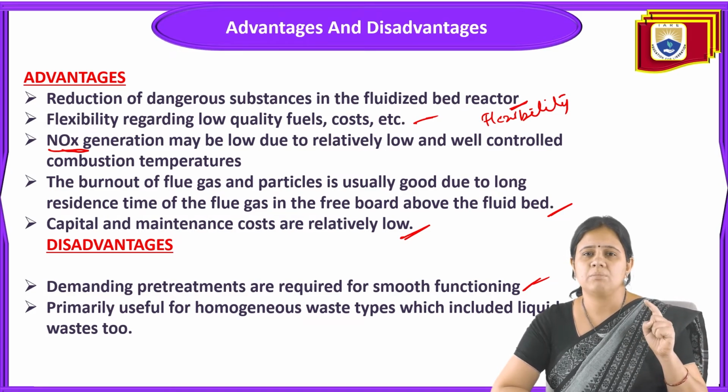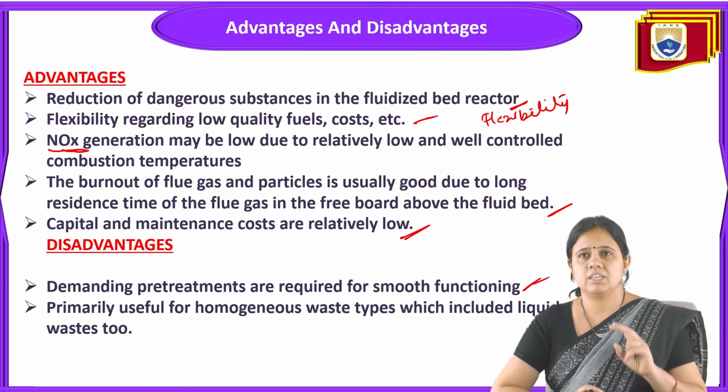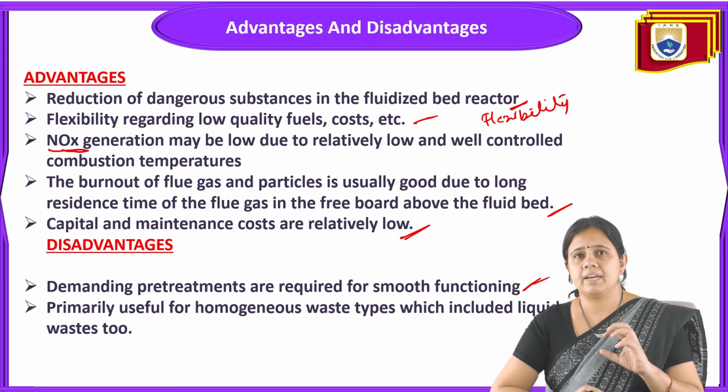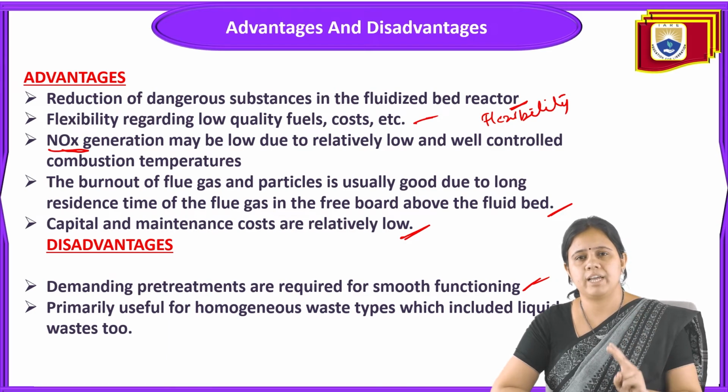Mostly, if we talk about the cost, it is cost effective, not much costly. NOx generation is relatively low, and it is controlled by the combustion temperatures. The burnout of the flue gas and particles is usually good, because the residence time is also more as compared to the other types of incinerator. So the residence time is more, the burnout is good, and NOx generation is low in this type of incinerator.